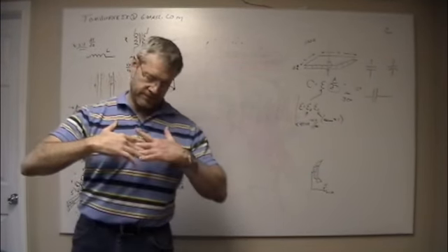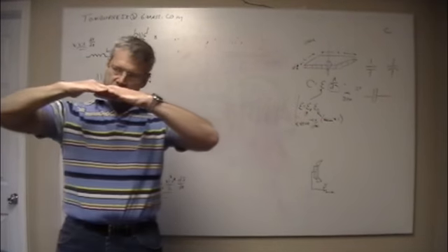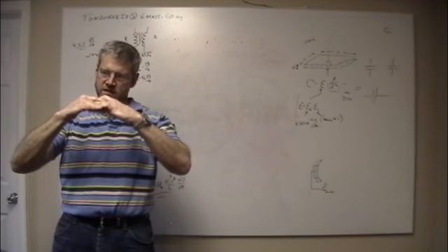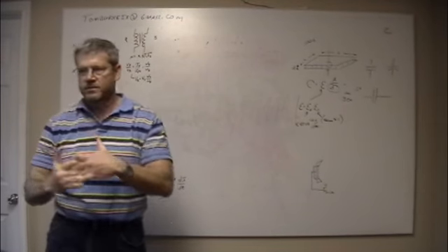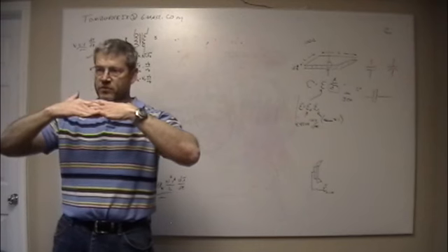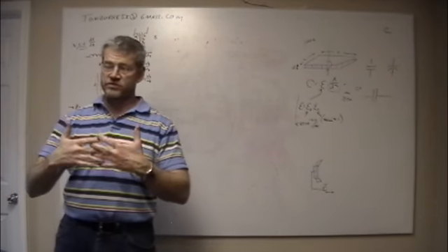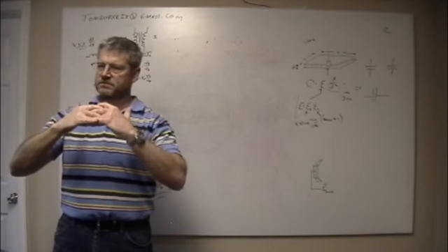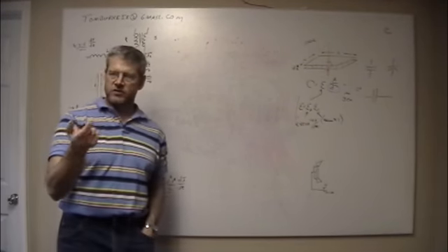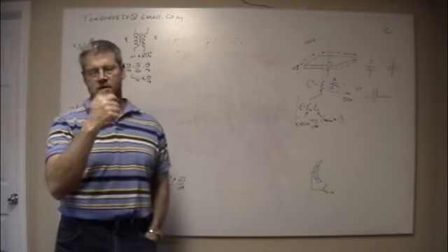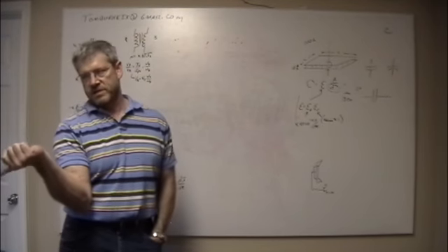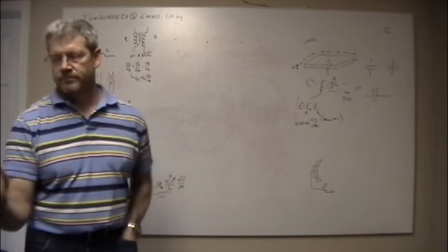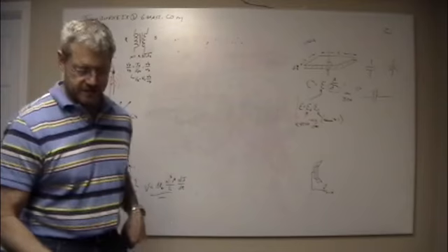So it's a stressed lattice crystal, and as you cause that lattice to bend, it creates a charge differential across it. By the same token, you can measure the voltage off of it, but you can also turn that around and use it as a speaker, because as you put voltage on it, it causes it to flex. So a piezoelectric material can be a speaker, or it can be a microphone pickup, depending on how it's made and what they use it for.